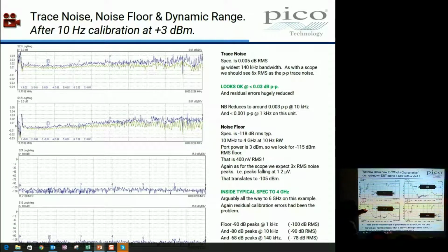It is a reciprocal device. I know there are some small differences down in the noise floor here, but it is a reciprocal passive device. And S22 is very similar, but it is slightly different. We now know this to be the low pass filter that we thought it was. We've got accurate measurements of its insertion loss, which is very deep indeed and couldn't possibly be seen by our oscilloscope. We know that it's got a little characteristic out here.